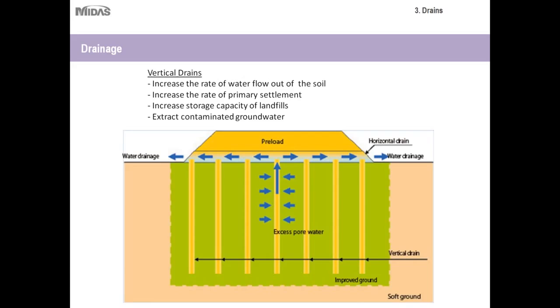So typically, when engineers enter an area with very saturated clay layers, they'll do drainage just to make sure that the settlement occurs very quickly. They'll install these drains, and they'll also apply their own load on it to increase the consolidation, or to increase the settlement. That way, they can drain all of the water out, all the settlement occurs, and then afterwards they'll build their structure, and there'll be a very minimal amount of settlement.